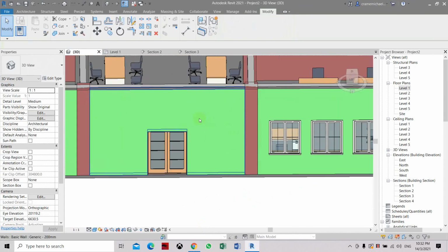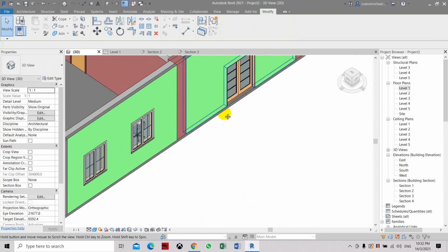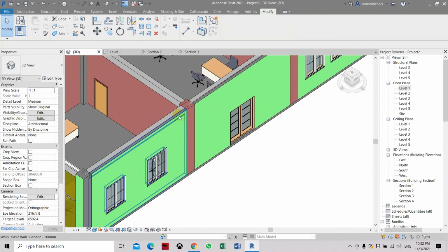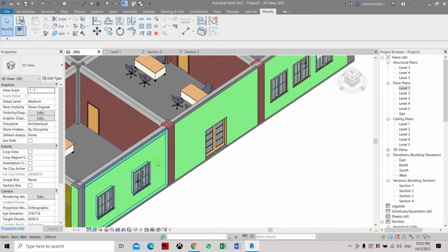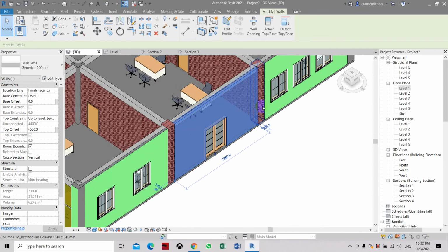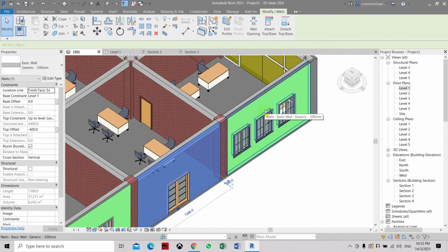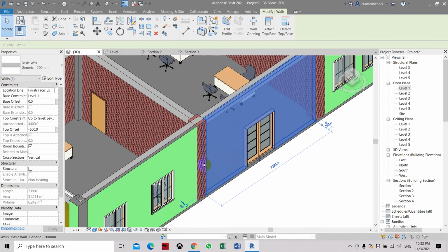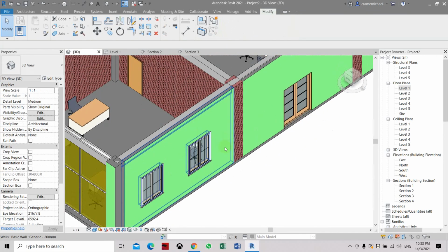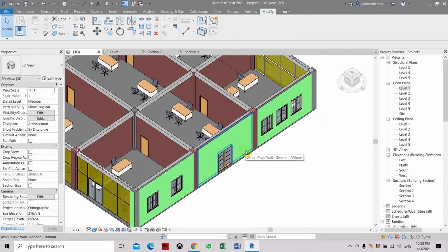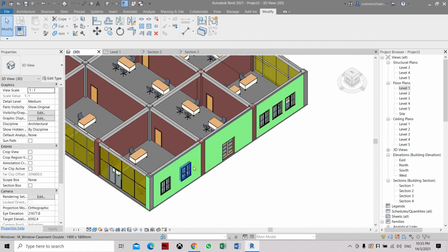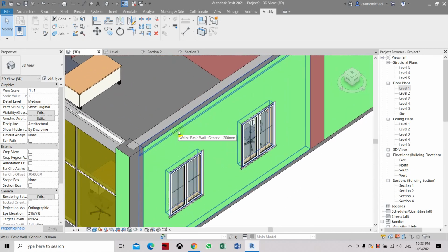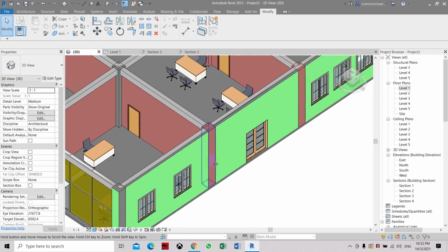So that is how to adjust and cut the joint walls, to modify the walls into different sub-elements or different wall elements, so later on you can place or paint or change the property for each wall element. This is the proper way for it to be constructed, so we just have to follow the same procedure when we model the wall and the structures.